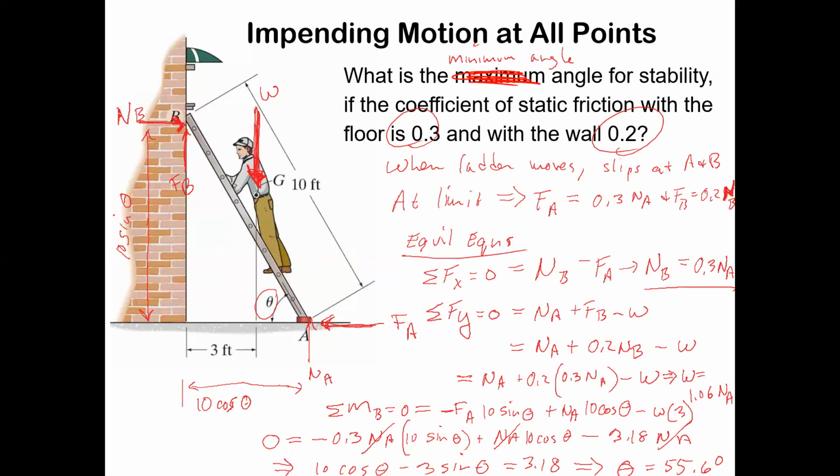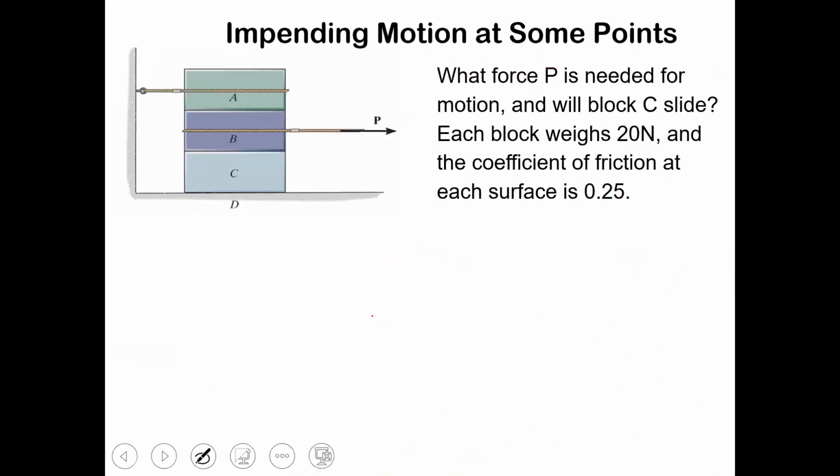And that means if the angle of the ladder is less than 56.5 degrees, somebody who stands on it is going to find the ladder slips down and away from the wall, right? So all that is pretty fascinating stuff, and you can go back and pick that up later if you missed some of that.